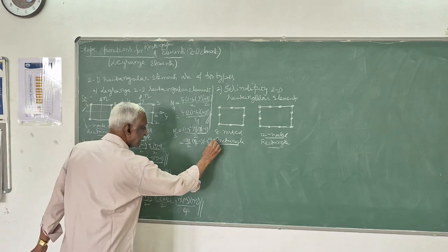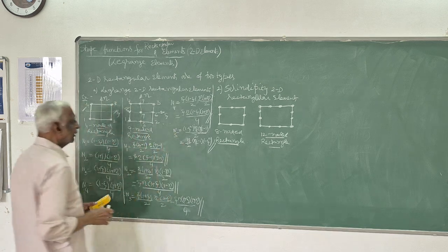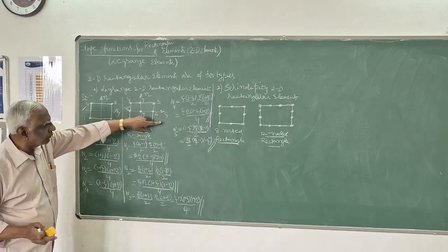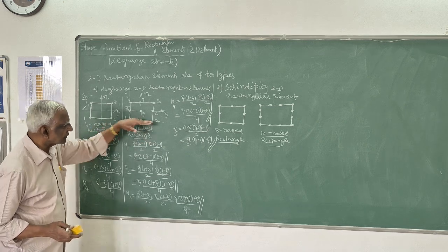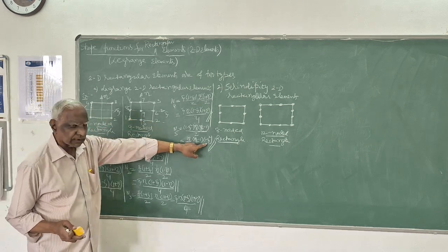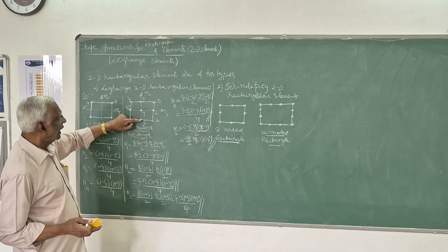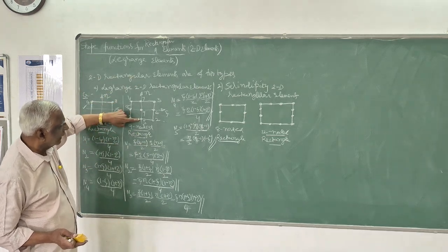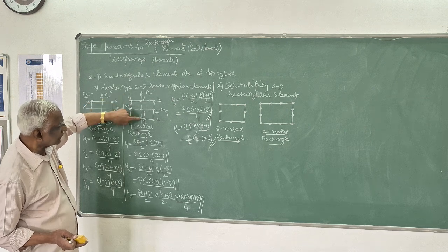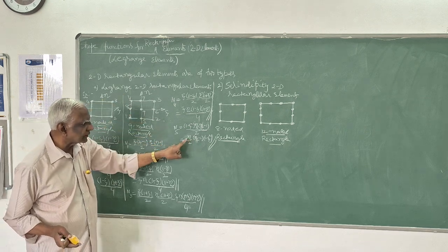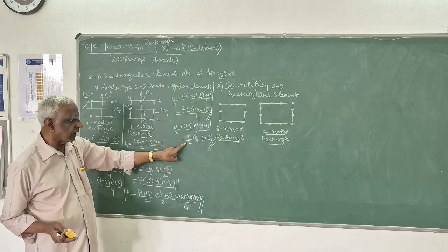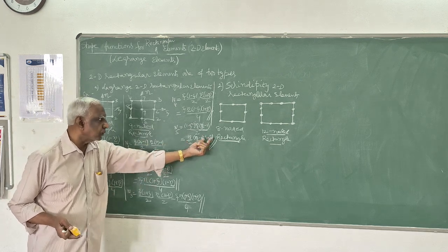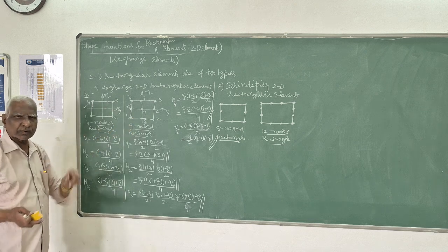In the middle node for side 1, 2, along the psi direction, that is 1 minus psi square, and for the eta direction this is the first node. For the first node of a 3 node element, the shape function is eta into (eta minus 1) by 2. So the tensor product of these two is the shape function for N5.